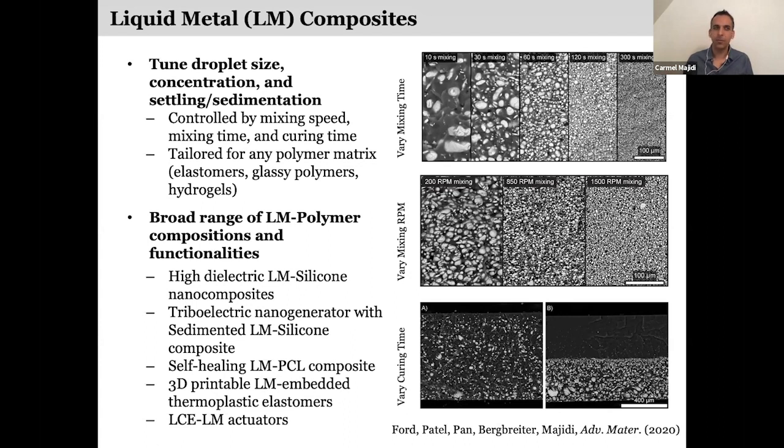Now, going beyond that 50%, you get even more electrical conductivity. That's not something that we've systematically looked at, but it is something I would expect. If we go to the farther extreme, then we start bumping into some of the work that Rebecca Kramer's group had shown previously, where they had very high concentrations of liquid metal droplets with no surrounding polymer matrix material. The concentration was really just limited by whatever air gaps you had or whatever surfactant you had on the liquid metal. In those cases, when you mechanically sinter, you pretty much restore the bulk conductivity of the eutectic gallium indium. And so, to answer your question, there is a percolation threshold, and you would get increasing conductivity as you go to higher and higher concentrations of liquid metal.